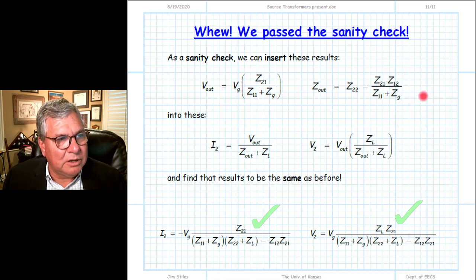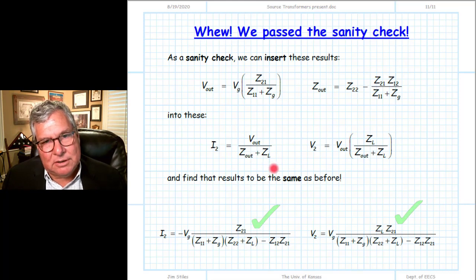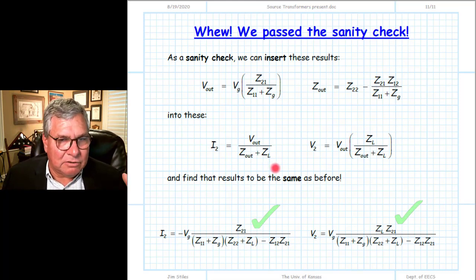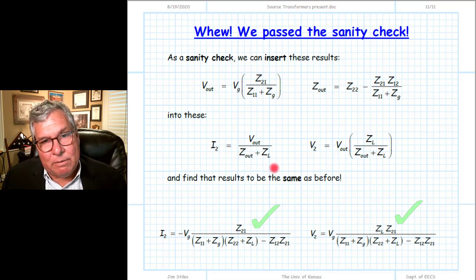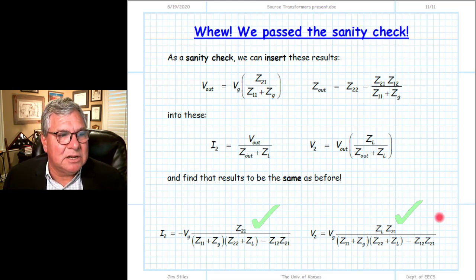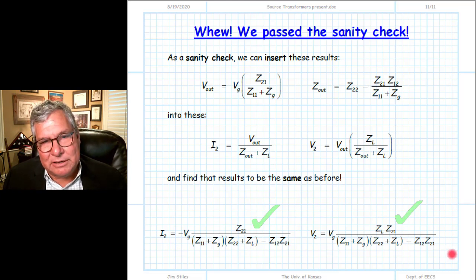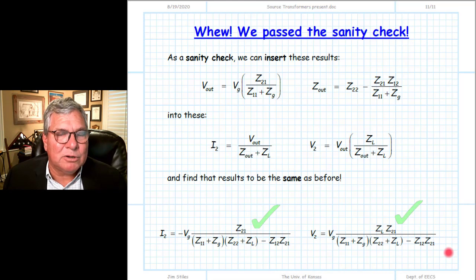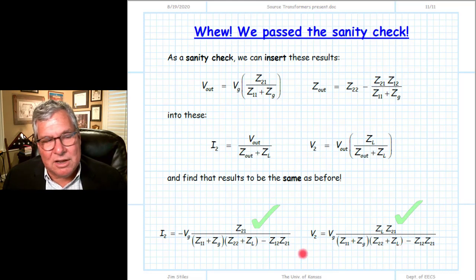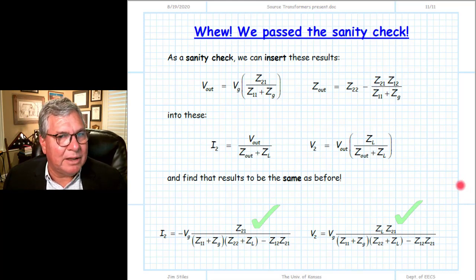Again, in this class, really what we always want to do is come up with a source transform and an equivalent source, and then do our algebra. Not only is it easier, I think, once again, the transformed source will tell us more physically about what's going on in our circuit and what our two-port device does. So I write these equations here for completeness and to show you that our transimpedance parameters for our two-port device and our equivalent circuits are sufficient for finding these currents or voltages, but I don't really ever want you to use these equations. There's no reason why you'd ever use these equations to find a value for current or voltage or power. These are the ones that I think in almost every case are the simpler and more insightful way to get those results.